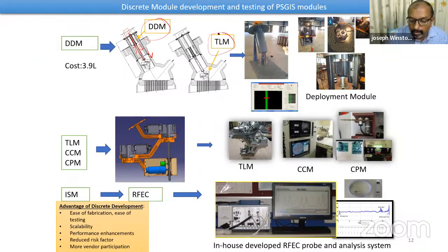Then the tube locator module is the robotic arm. Here you can see the complexity of the 2-axis robotic arm. Here there is a motor and here there is a motor. These motors work with very high resolution encoders, 5000 PPR with quadrature, and also 200:1 gear ratios. So it's somewhere close to 2 lakh counts. We get 2 lakh counts for 1 rotation.